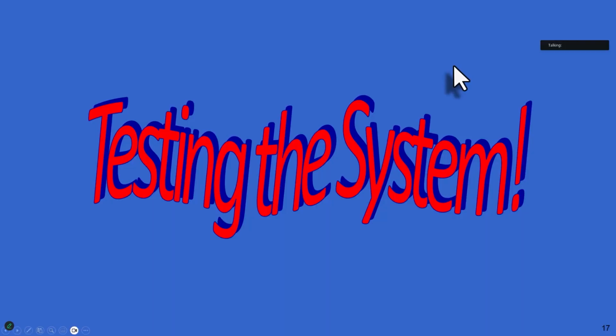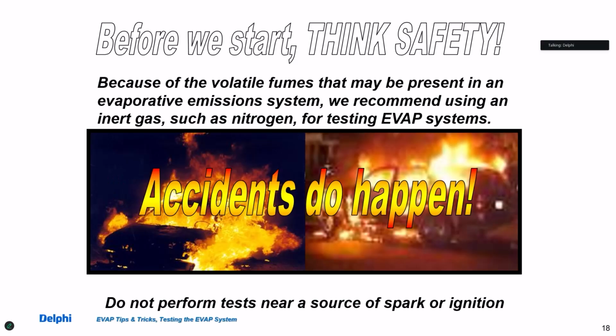Okay, testing the system overall is pretty straightforward, but there's a couple things I want to go through before we go any further. One of them is safety. You are working with fuel. You are working with air, and all you need to start a fire is a spark. So if you put air into the EVAP system and you have a leak, you're creating a wick to the outside. If there's a spark in a nearby area, it can ignite. And when I say ignite, it can light, get into the tank and create a fire.